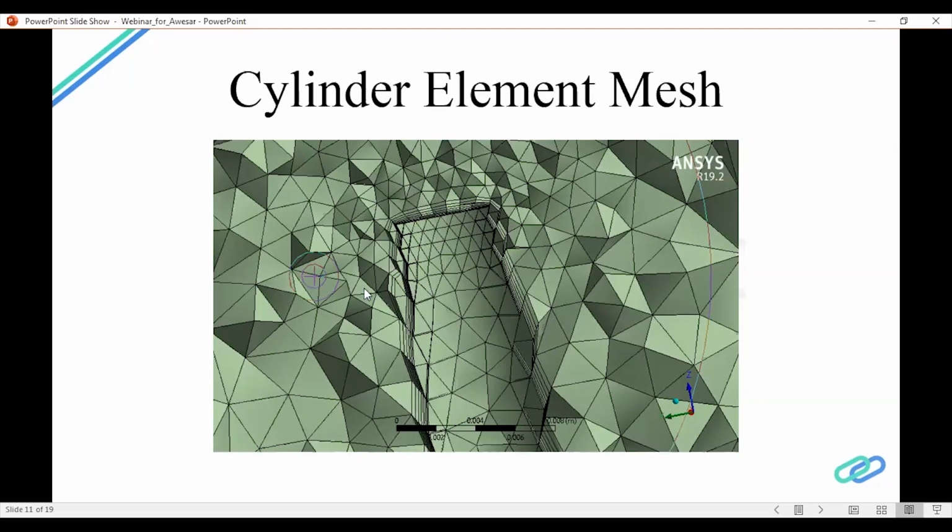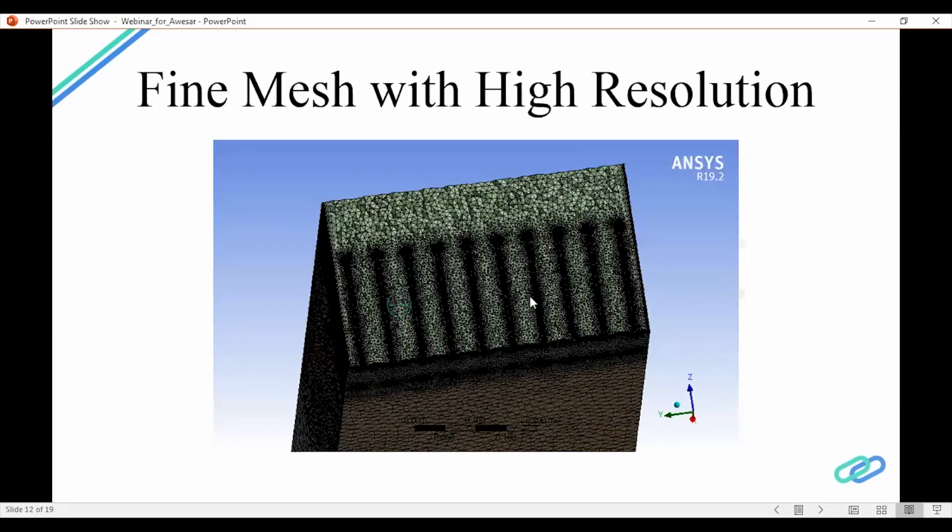Now the vegetation, because it has a very high drag coefficient, will slow down the river velocity, the water speed. When it slows down, it will cause flooding. It will come out of the river channels to the left and the right, then cause damage. Now, this is another view of the mesh. When you want to design a mesh, you need to make sure, as I mentioned earlier, to use CFD work properly to come up with accurate results by having a very high resolution mesh.